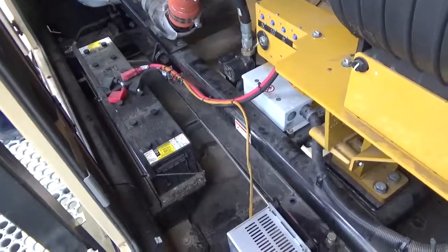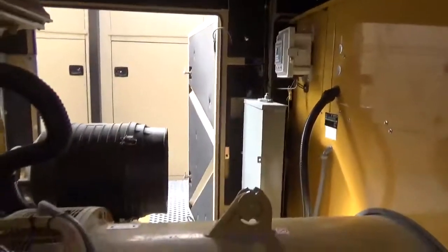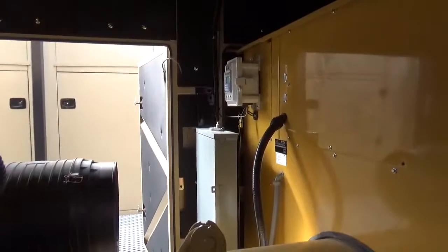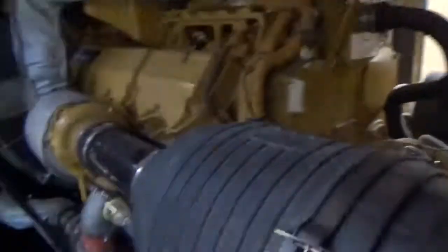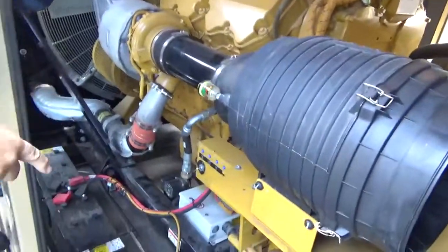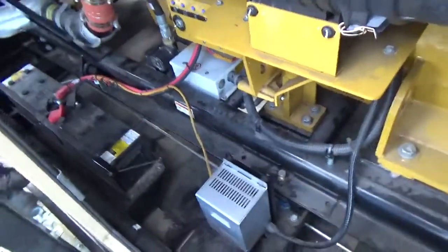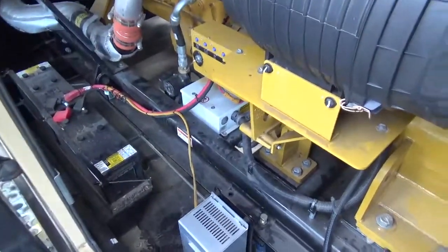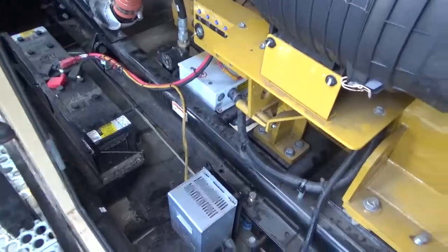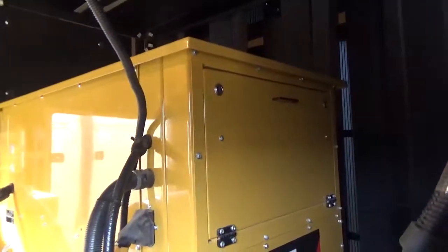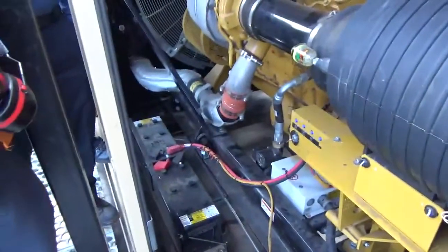Is that in that panel over there? Since it's not listed, it's probably coming from the one that's labeled jacket water heater, because that'll kill power to this panel up here, which will in turn power off that. So we can't isolate the charger with just a breaker? There's probably one of those breakers in there strictly for this. So that's the breaker that we want to look at.